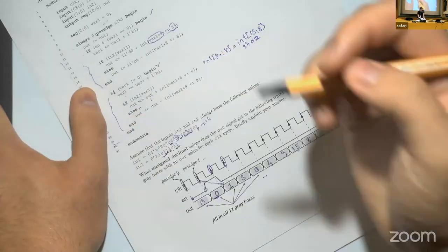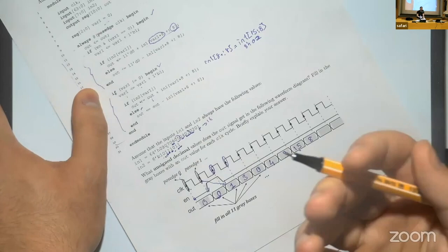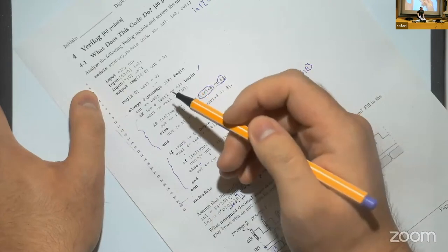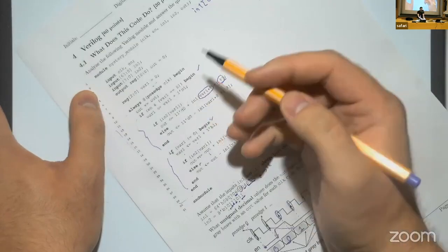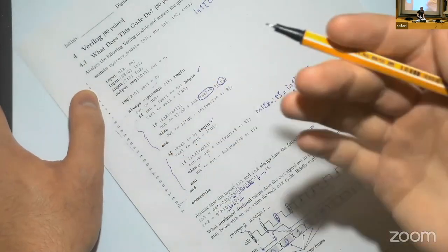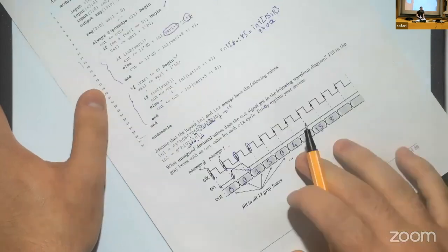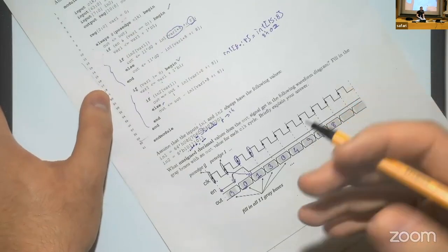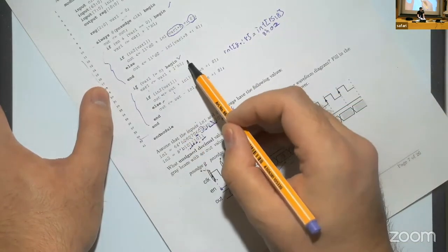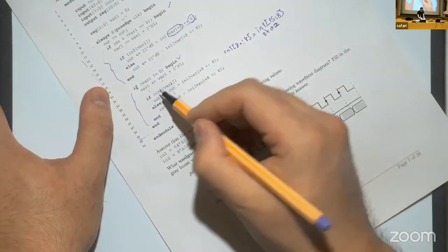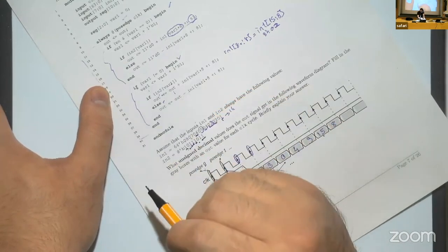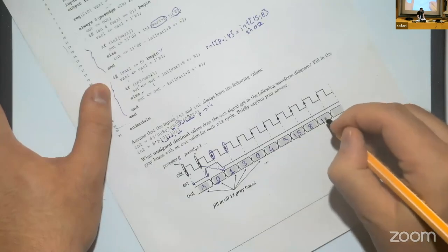So we increment var1 by 1, which makes it 8. But the problem here is var1 is 3 bits. So 8 is actually 4 bits, right? 1, 0, 0, 0. What happens is that var1 takes the least significant 3 bits, which means that it resets to 0. So in the next cycle, var1 becomes 0 again. But let's execute this cycle. Where var1 becomes 0 here, we check the 7th bit of in2, which is 1. Then we perform addition, 8 plus 8, which is 16.